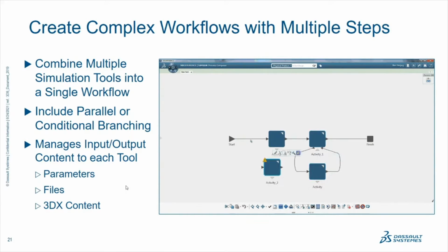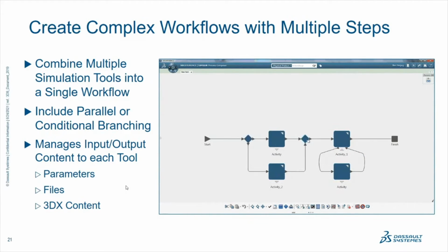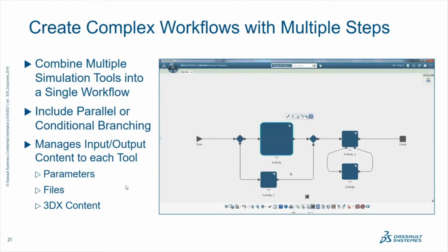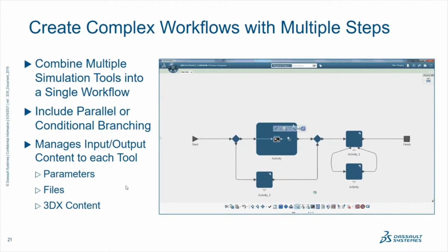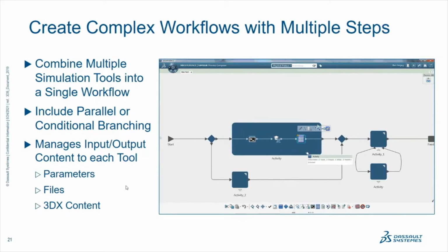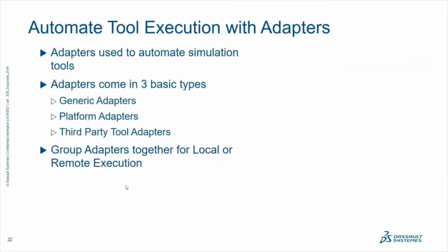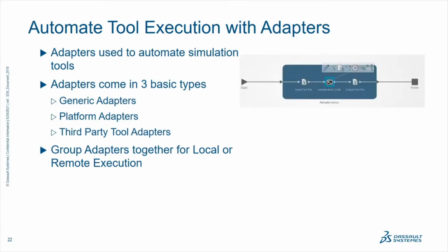Also, you can configure Process Composer to manage all of the input and output content associated with each tool. Things like the parameters that are required for each tool to execute, any files or data that is required at runtime, and any 3D Experience platform content that may be required as well. So you can really automate your simulation process through Process Composer by use of adapters.